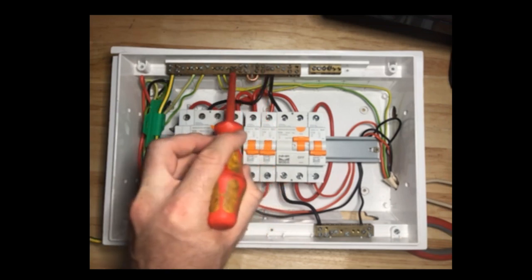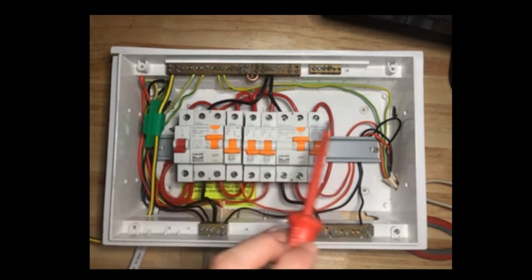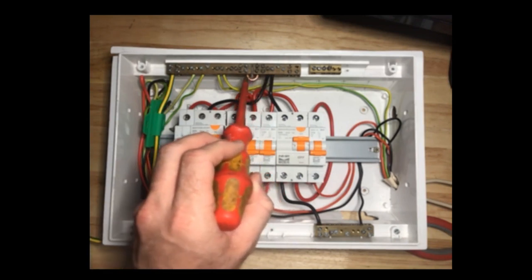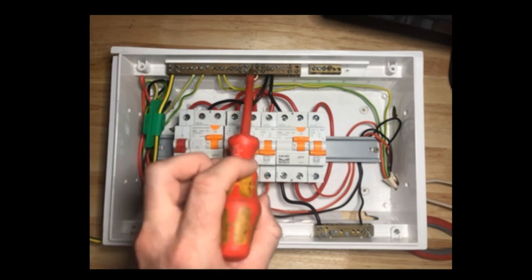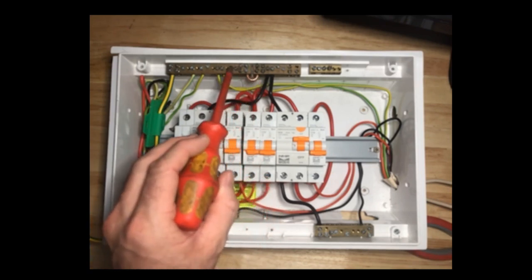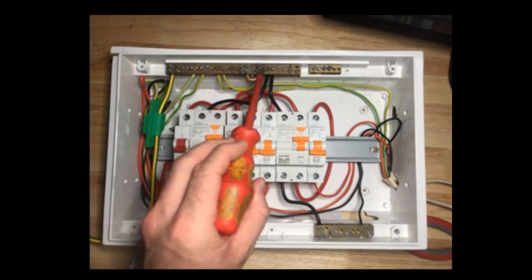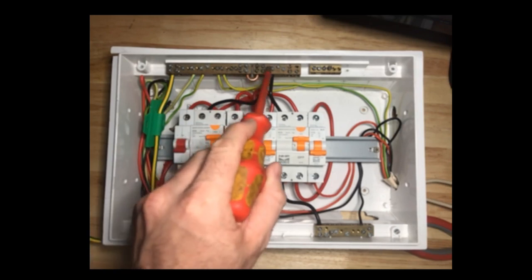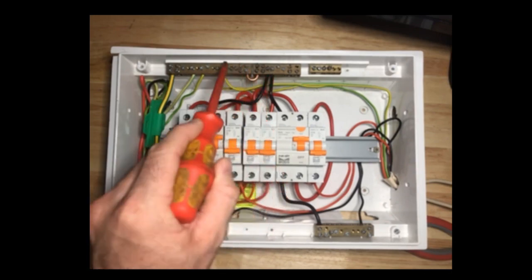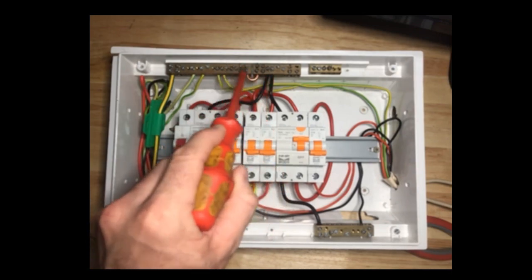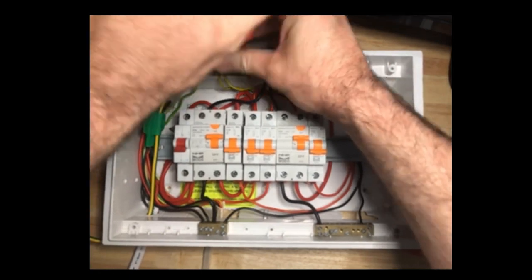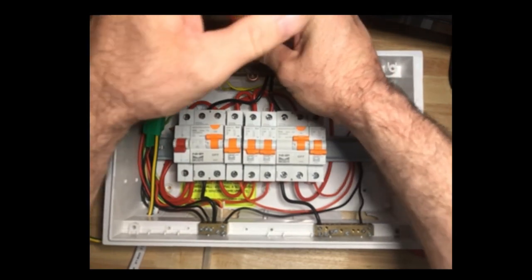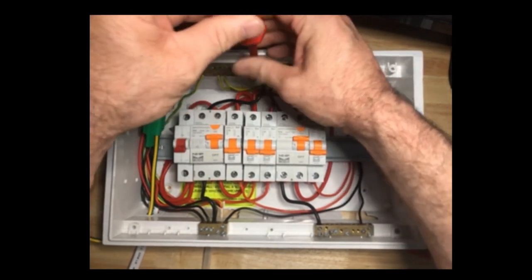I also need to test between neutral and earth, because in this case, neutral is considered a live conductor. So you'll see here I've got my bus bar link, my MEN link between my neutral and earth bus bar. Obviously, if I test for resistance between the earth and neutral bus bars at this point, all I will get is the resistance of that link. What I actually want to do is make sure that nothing that's connected to the neutral bus bar is connected in any way to anything that's on the earth bus bar. So I'm going to need to remove that, and I'll do that now. We need to remove that in order to ensure that we do not have a link between my neutral and earth when I'm testing.